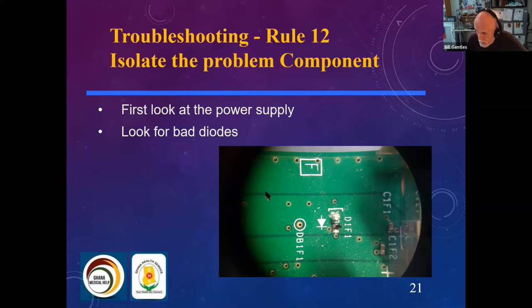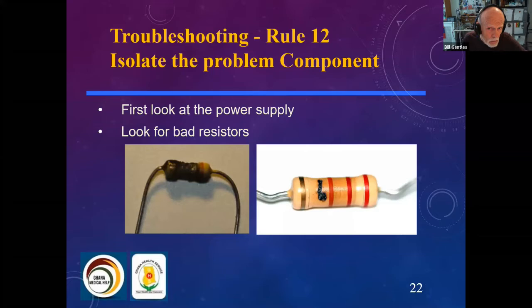Typically, if the electrolytic capacitors have failed, they may have gone to short circuit, and as a result, consequently blown some of the rectifier diodes. So a failed capacitor may lead to the failure of other components, such as diodes. In addition, it can cause overheating of resistors by a shorted electrolytic capacitor. And this can often be seen by just looking at the resistors for carbon deposits or signs of overheating.